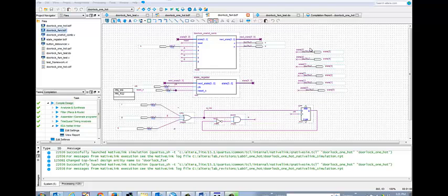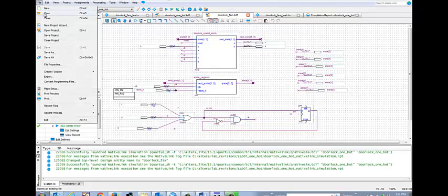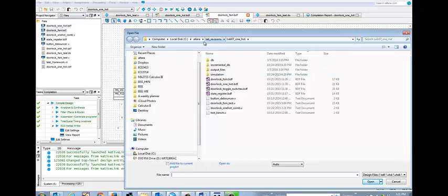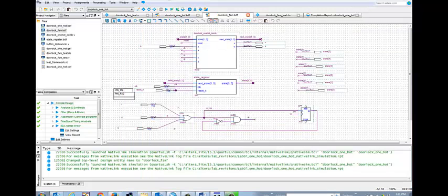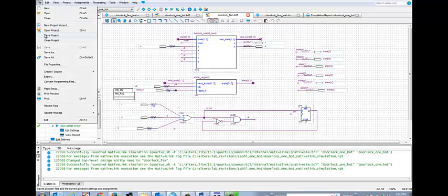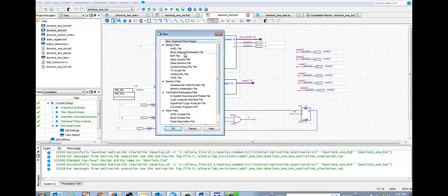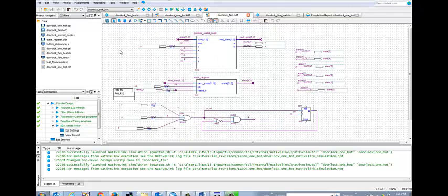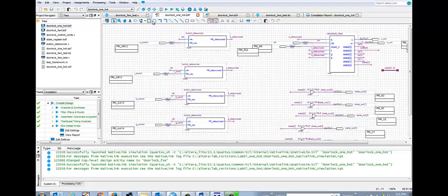All right, so once we've run ModelSim and returned back to Quartus II, we can go ahead and create a symbol of our Doorlock FSM BDF, and then add a new schematic. We want New, and then a new schematic file. Click on that, and then we can call it Doorlock One Hot, which I've done. I've added the button debouncers, and I have my Doorlock FSM symbol that I've created.